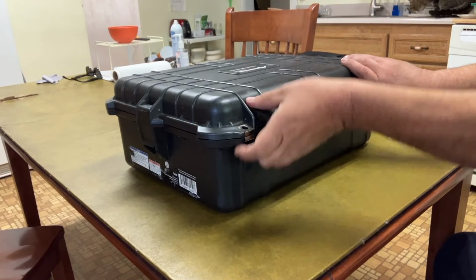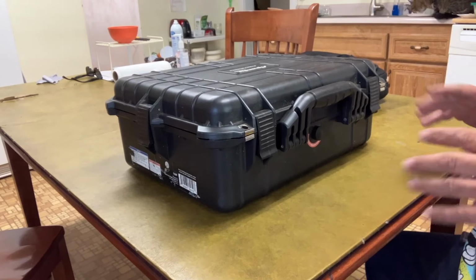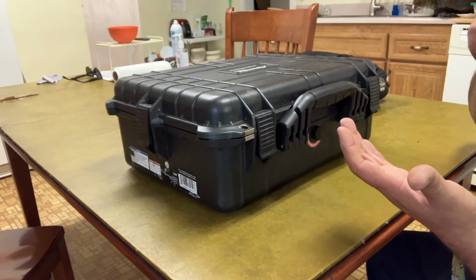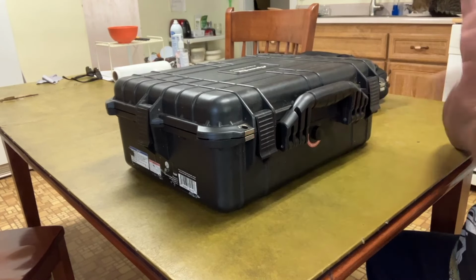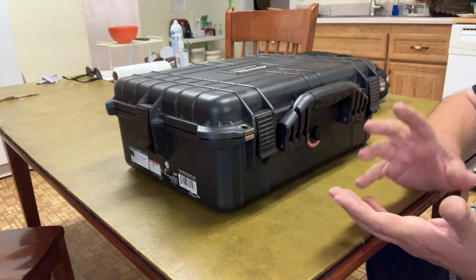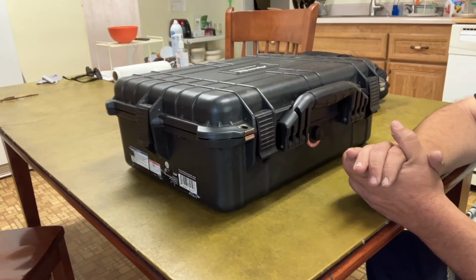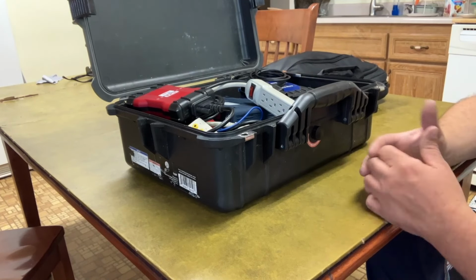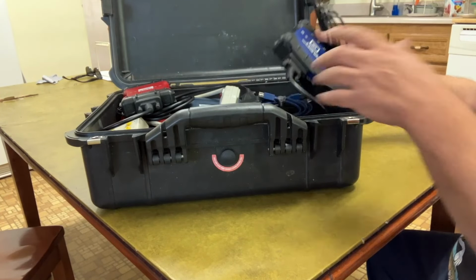First, I keep all my programming stuff in this Apache case, and I don't program European cars, Eurotrash stuff like that. Mostly, I have just programmed GM, Chrysler, Ford, and Toyota and Honda. I've only done Toyotas once and Hondas twice. Hondas are really easy. If you get the same computer, I shouldn't even say program, because you can just change the VIN number with the scan tool. But if you actually have to load software, that's different.